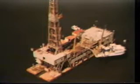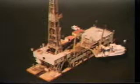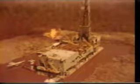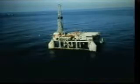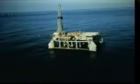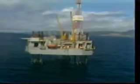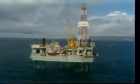Offshore drilling rigs fall into one of several categories, each designed to suit a certain type of offshore environment, primarily water depth. The barge rig is a flat-bottomed vessel which can be towed to a drilling location and ballasted to rest on the bottom of a shallow lake or swamp. A submersible rig is a larger version of this type, capable of maintaining stability for work in deeper waters. Self-elevating or jack-up rigs are designed to float to a drilling location with their legs in the air, at which point the legs are jacked down to the seafloor, lifting the drilling deck above the waves.